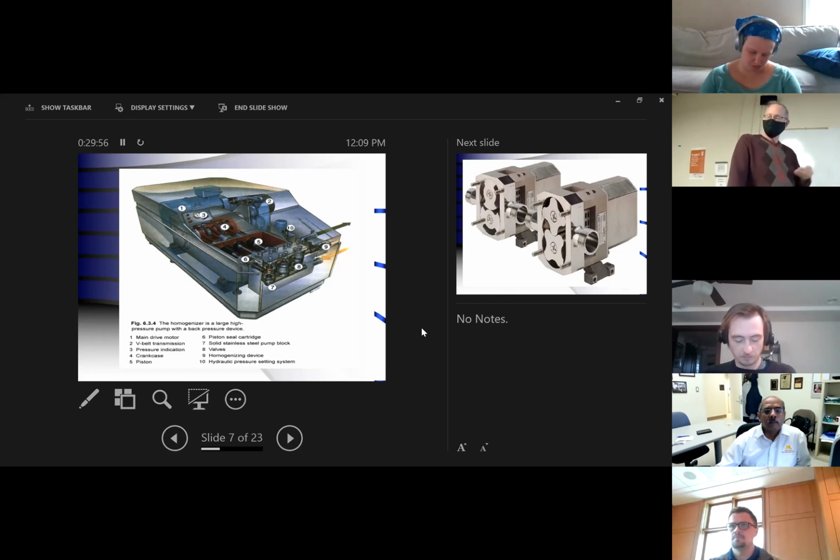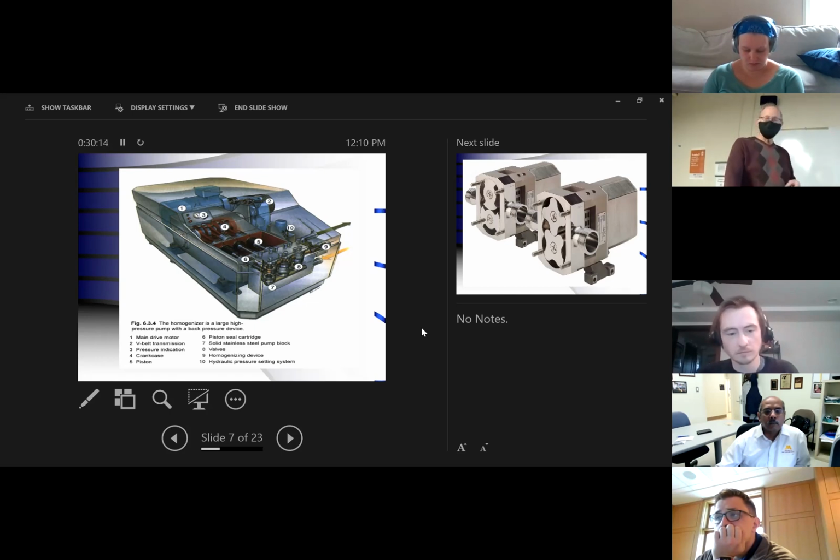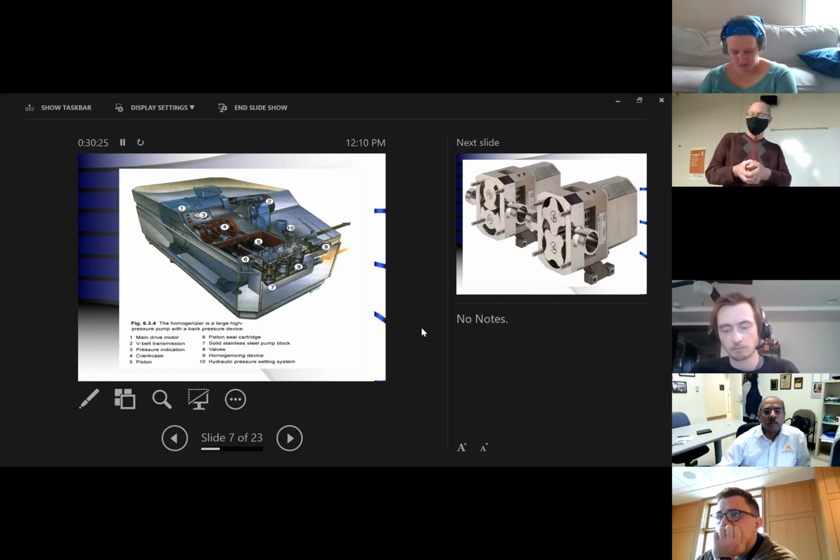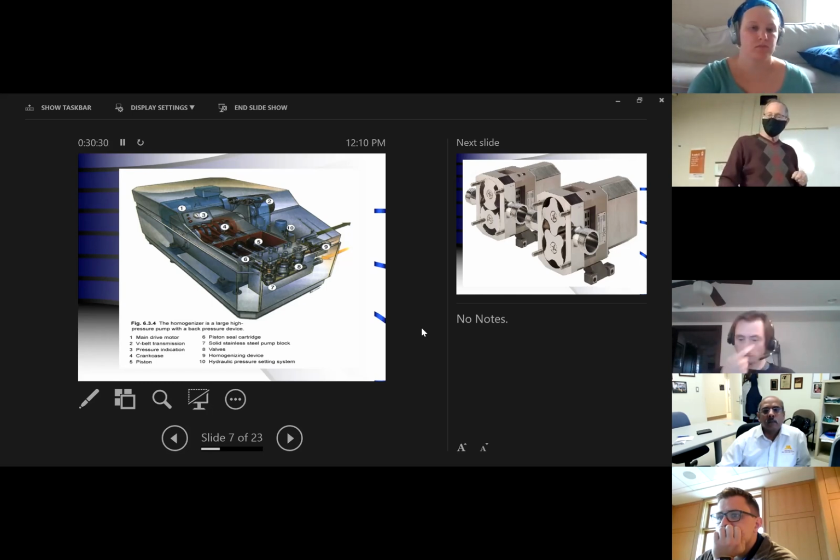Again, another place that we used a pump exactly like this was in the membrane processing lab. To maintain those pressures, we had a small positive displacement pump, and those of you that were there for lab remember there was water on the floor. Well, one of the things you have to do, because you've got metal basically sliding through metal, is you need to maintain a cool environment or you just burn the pipes up. The system would freeze, the metal would expand, and you'd have bad things happening. So that water is there as heat removal.